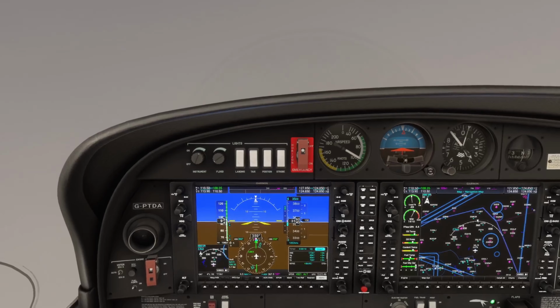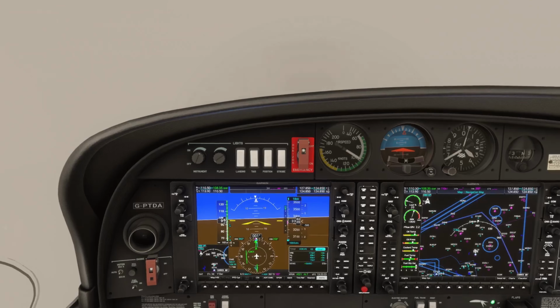So we now need to descend to 1,800 feet. So 1,800 feet set, T's and P's in the green, 1002 cross-checked, and start our descent. So now we're pulling the tail round to set it on that outbound course of 358, and we're just going to maintain the heading down the approach path. We want to get to 1,800 feet before we start our turn, just to reduce the workload as we eventually get there.